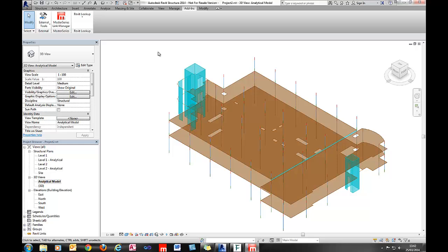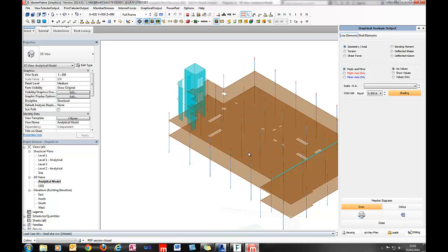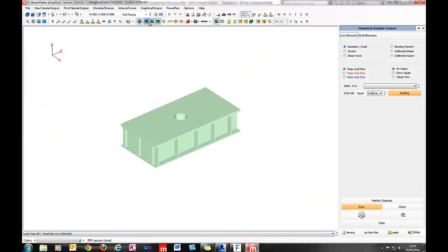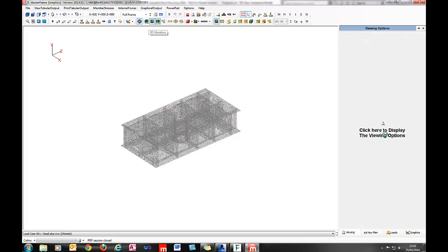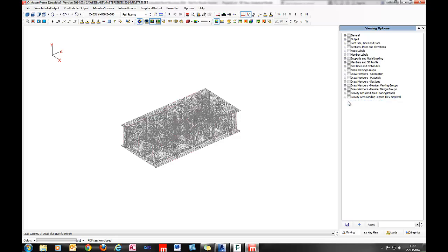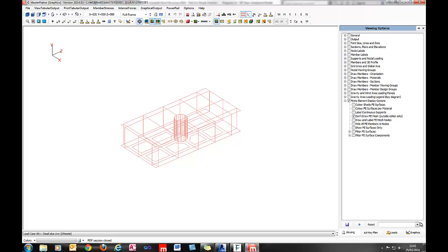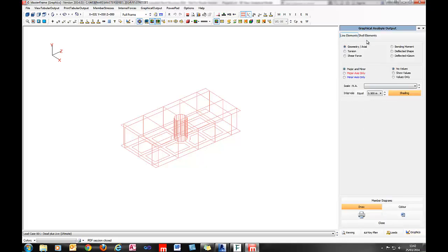And I think we've got a very fine mesh here, so it's quite a considerable amount of contouring to draw and such. So we'll just go into shell elements. One of the things I want to do here is just go into my finite element display options. Naturally this isn't new, but it helps me here, and just say don't draw the mesh. Let me just see the plane geometries, and into shell elements.